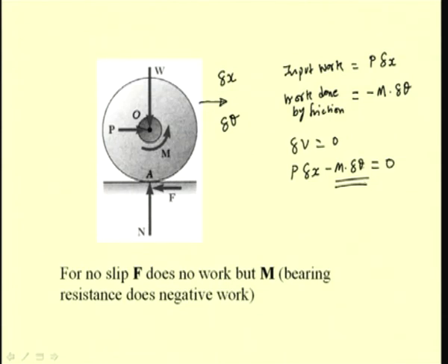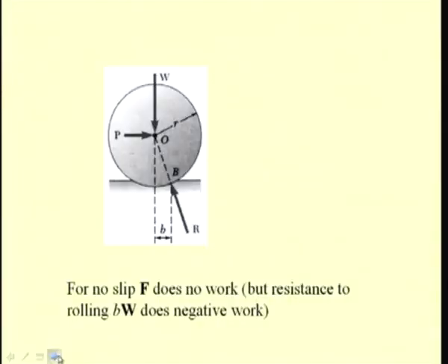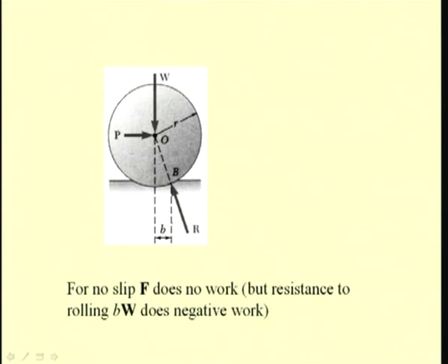So, in real systems we see that a negative component of virtual work exists for each of the frictional effects, either sliding or in case of pure rolling motion. Let us see another case where we have rolling resistance. We have already seen that real objects are deformable, and so when a free wheel tries to roll on a surface, because of the deformation there is a rolling resistance,